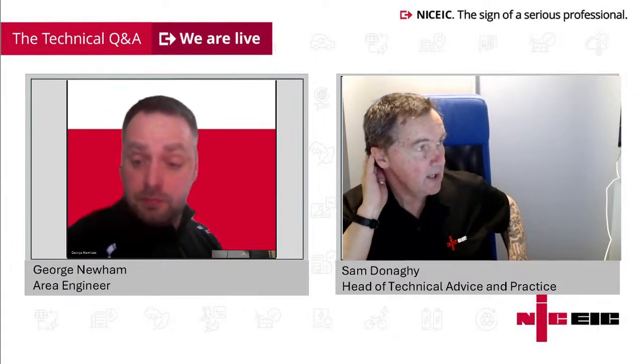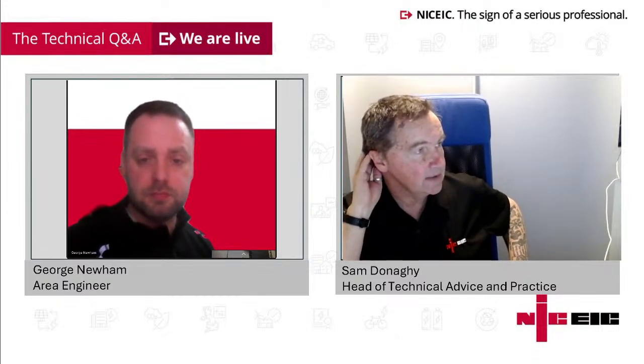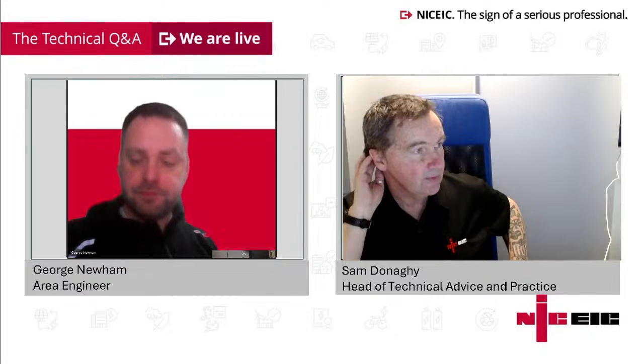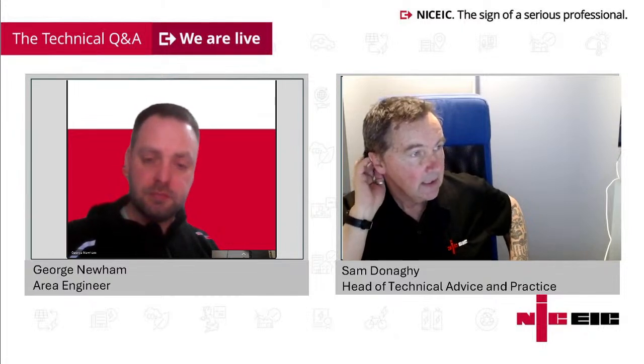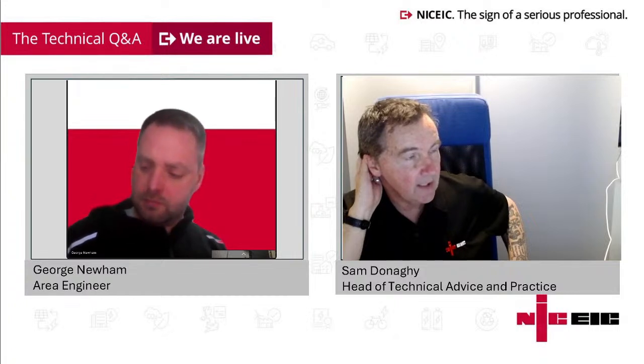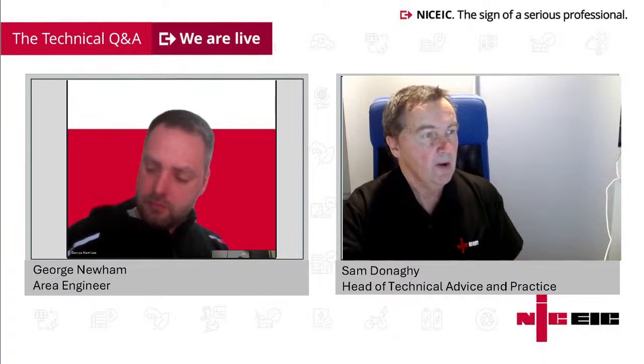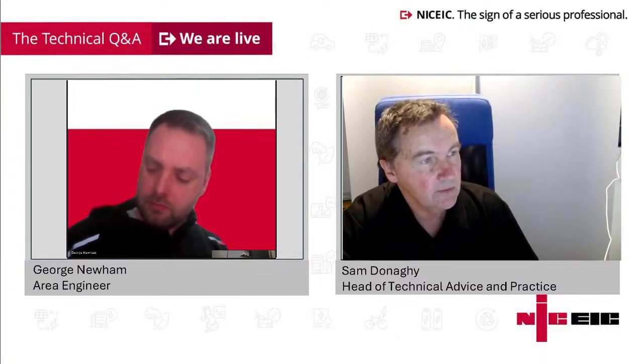We are doing a large office fit out. AC is being installed. 3-phase 45 amp supply, RCD protection. Would you advise we need to get MOD conversion to make RCD protected, or just on triple pole isolator? Thanks, we've installed